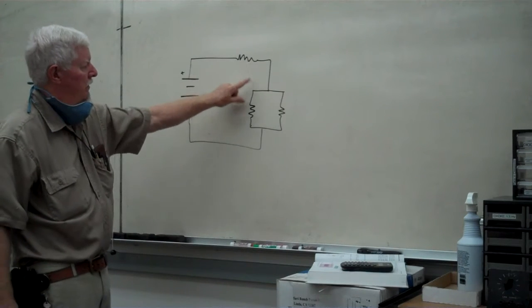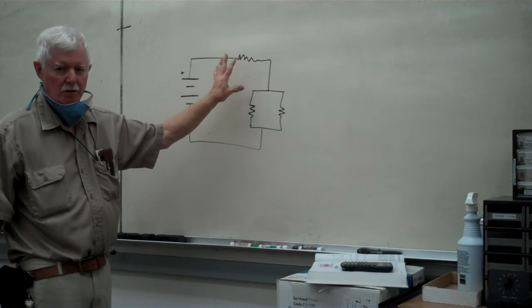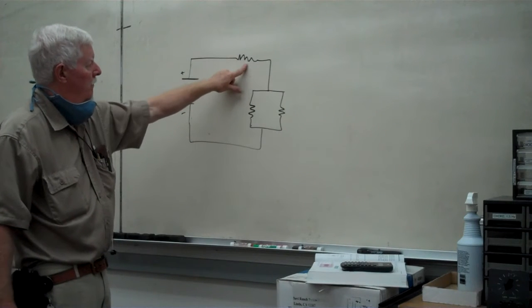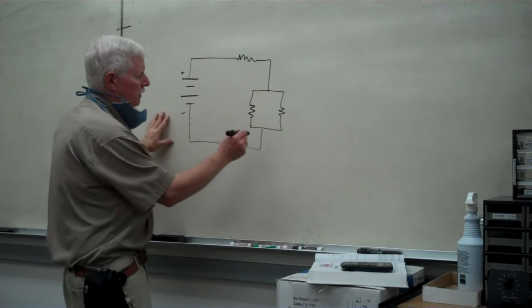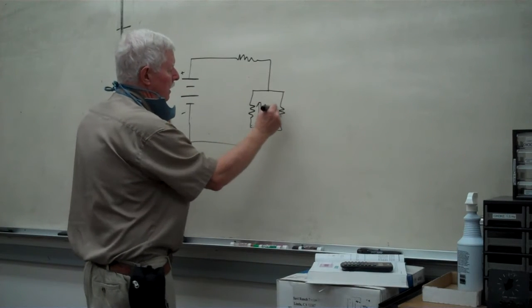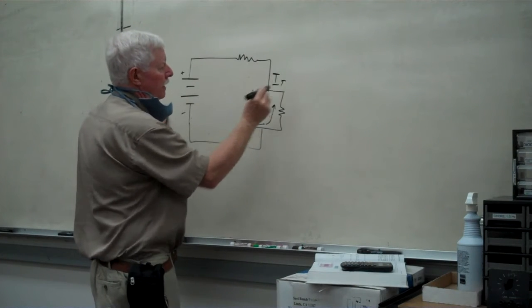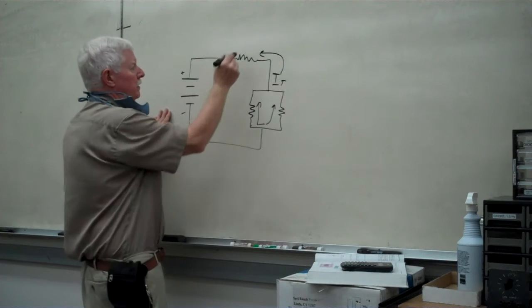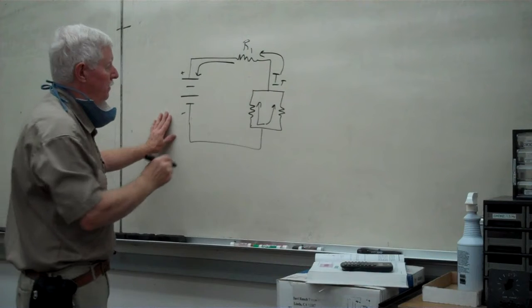This is what we call a series parallel circuit, and they're very common. In fact, most of the circuits you work on more likely will be of this style. We have the current that's flowing through the parallel branch, and it's going to divide in between the two. And we have the combination of the two currents as they drive out here in the form of the total amount of current goes through the resistor, label this R1, and back into the power source.